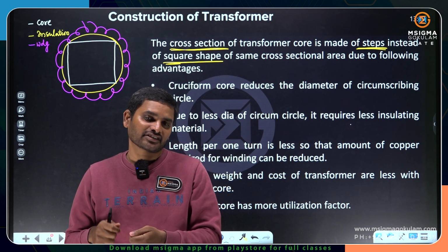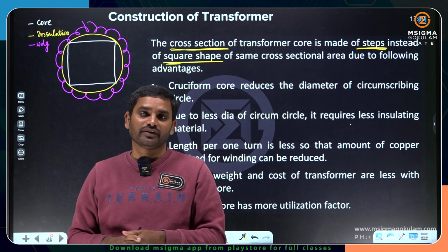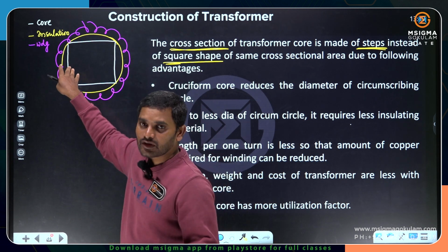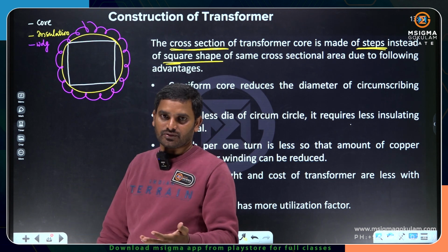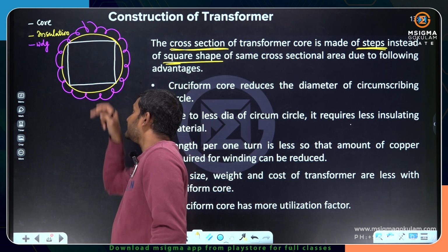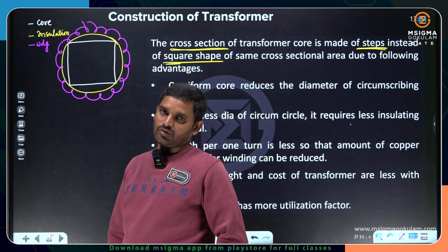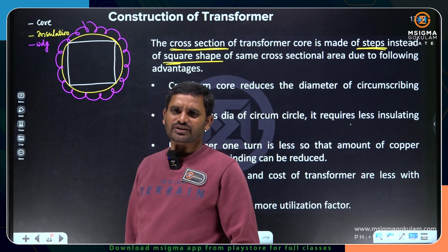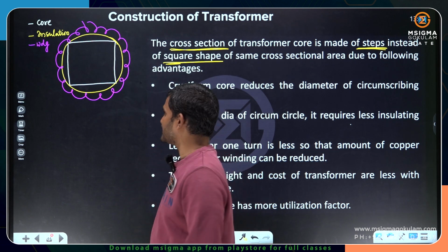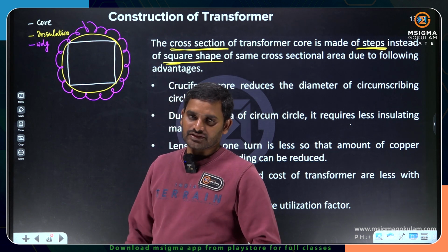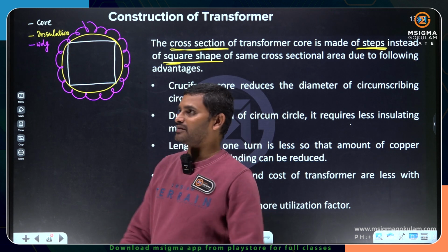It will have some electric potential and it will carry some current. Whenever you place the winding directly onto the core, it will lead to a short circuit, and a current flow in the core also. So, to avoid a short circuit problem and unnecessary current flow in the core, we place the insulation. The core and winding are separated by an insulating medium.